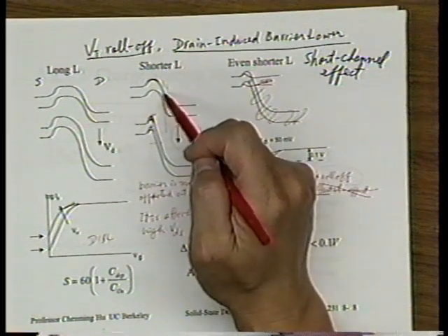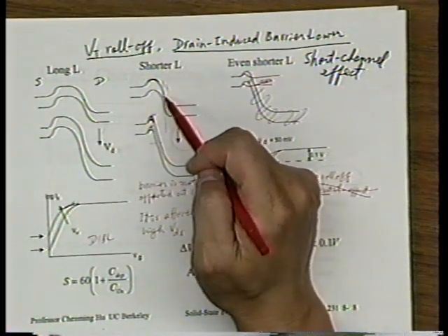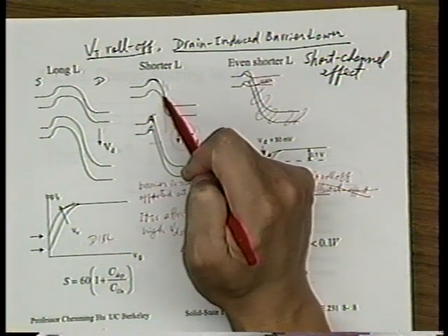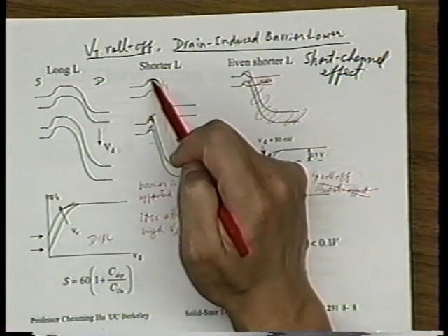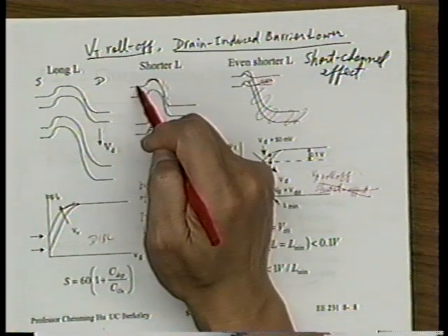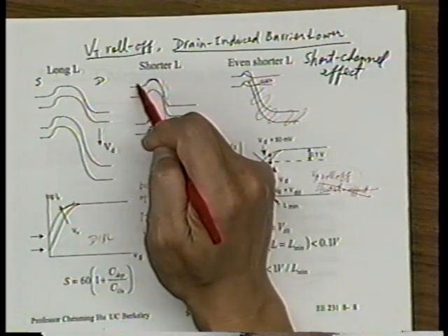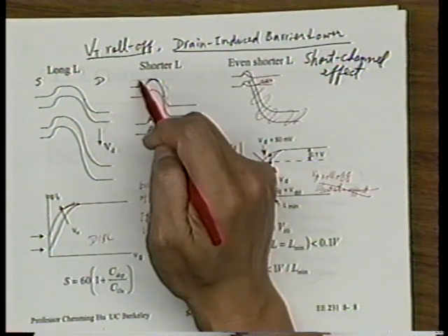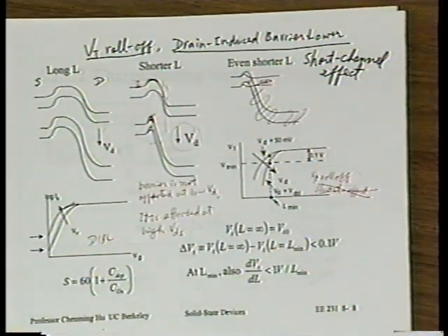So certainly I didn't argue that we should be looking at the barrier height right at the drain. If this is the metallurgical junction, no, this is the peak. So that part I agree with you. The important barrier here is the difference between the EC of the source and the peak of this whole plot. That's the only barrier we need to look at. So this barrier in fact is not a source junction barrier. Instead, it is a source to channel barrier. Absolutely, it's a channel barrier. That's the word I would use. All right, I think the lecture later will clarify this.